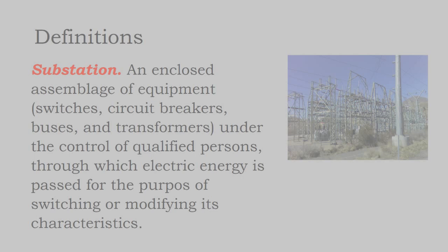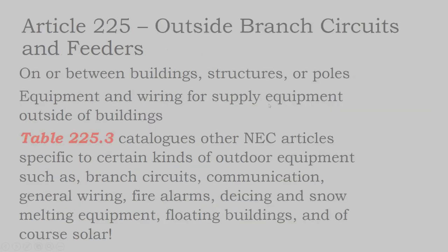And then there'll be another medium voltage conversion that'll step it down to your distribution circuits, and then another transformer conversion that steps it down to your power lines that come into your home, which are your 240 volt split phase, or 208 three phase, or 208 delta, 208Y.